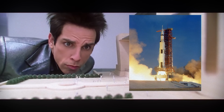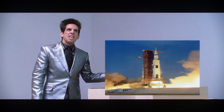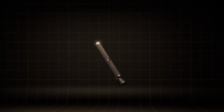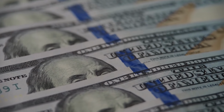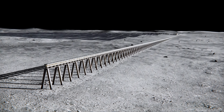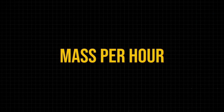And recall that of the two main ways to reduce peak power, we decided that lowering the mass of the rocket pod was more attractive than lowering acceleration, because if we lower acceleration, we have to increase the launcher length. But lowering the pod mass allows us to lower the mass driver size and power, but we lose out on economics as we would have lower throughput. But we can combat this by simply keeping the same sized launcher, so the launcher is not sized for any single shot, but rather for some amount of mass per hour for throughput.